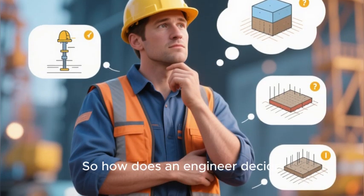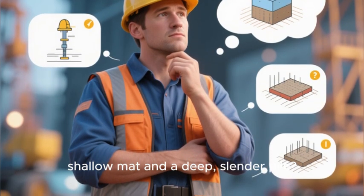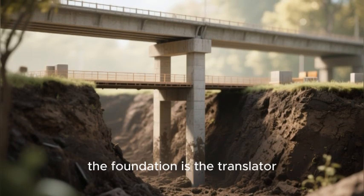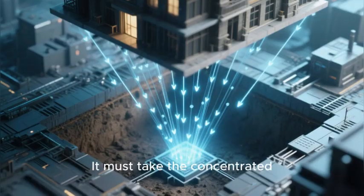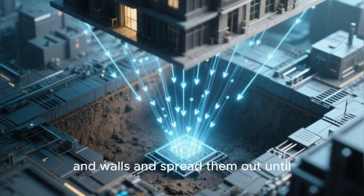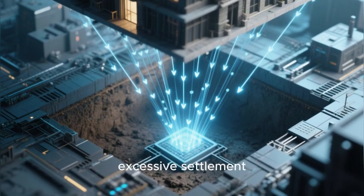So how does an engineer decide between a wide, shallow mat and a deep, slender pile? The answer lies in a simple but profound principle. The foundation is the translator between the structure and the soil. It must take the concentrated, high-stress loads from the columns and walls and spread them out until the soil can comfortably carry them without excessive settlement.